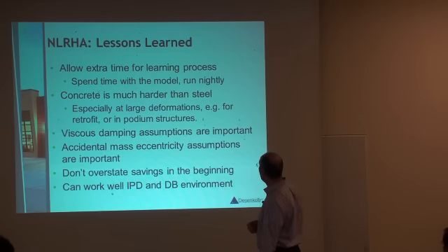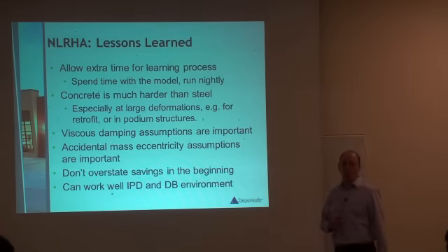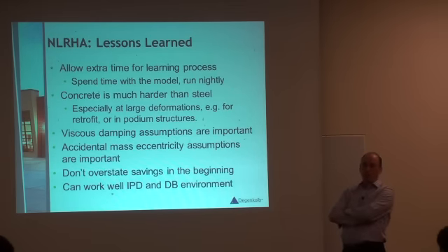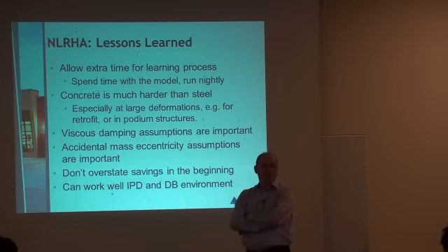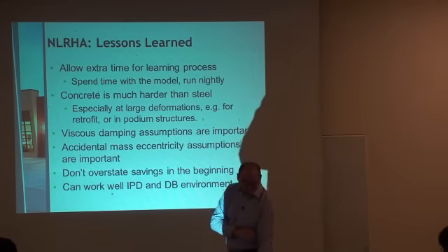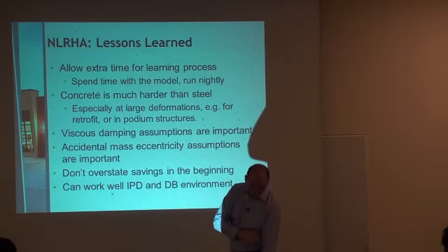Steel is easier to do than concrete typically because it's usually possible to use lumped plasticity models with steel without much loss of accuracy. With concrete, that's usually not the case. You have to use fiber models in concrete columns or fiber models with walls, which can be much more expensive to run. Not that you couldn't do it, but it's more expensive.